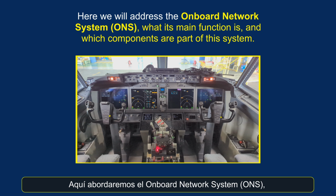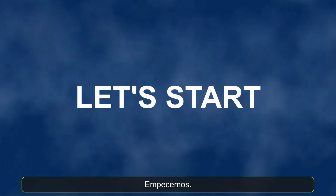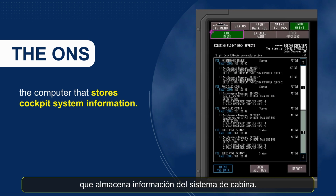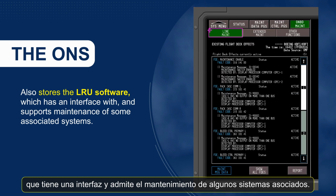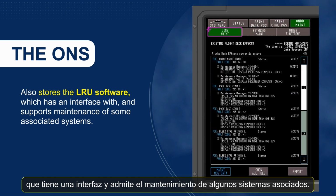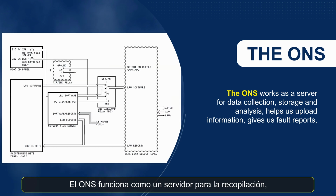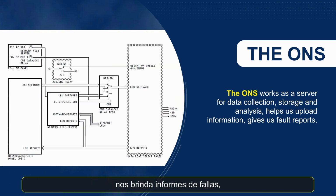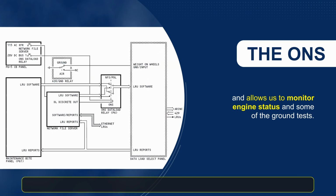Here we will address the Onboard Network System, ONS, what its main function is, and which components are part of this system. Let's start. The ONS can be described as the computer that stores cockpit system information. It also stores the LRU software, which has an interface with, and supports maintenance of, some associated systems. The ONS works as a server for data collection, storage and analysis, helps us upload information, gives us fault reports, and allows us to monitor engine status and some of the ground tests.